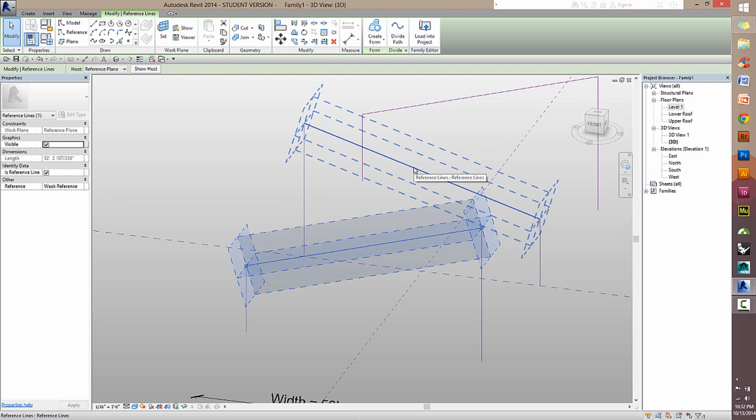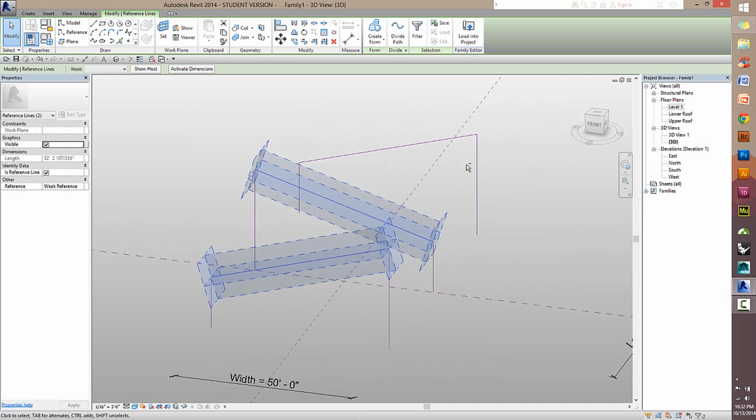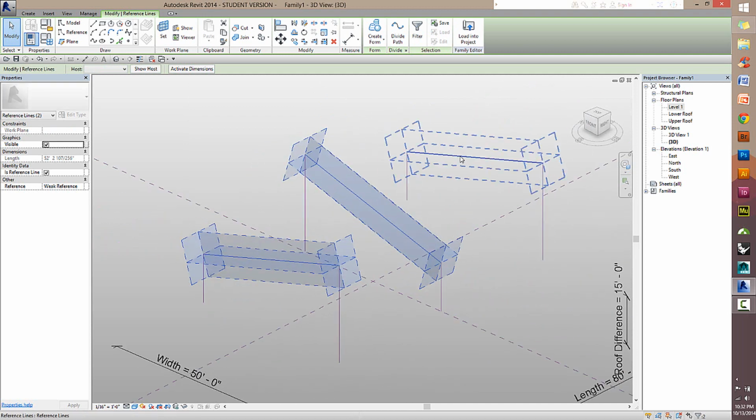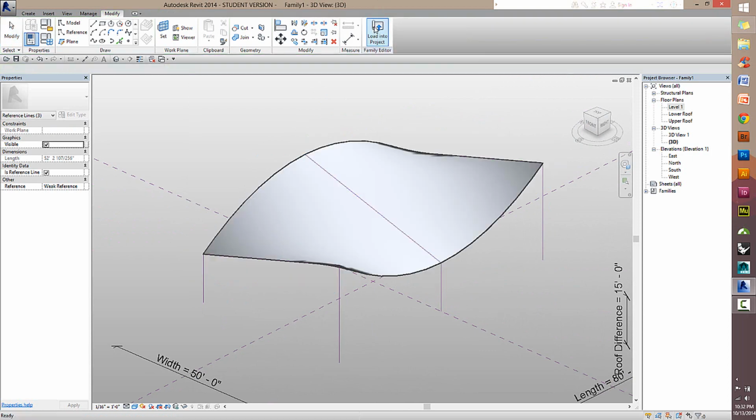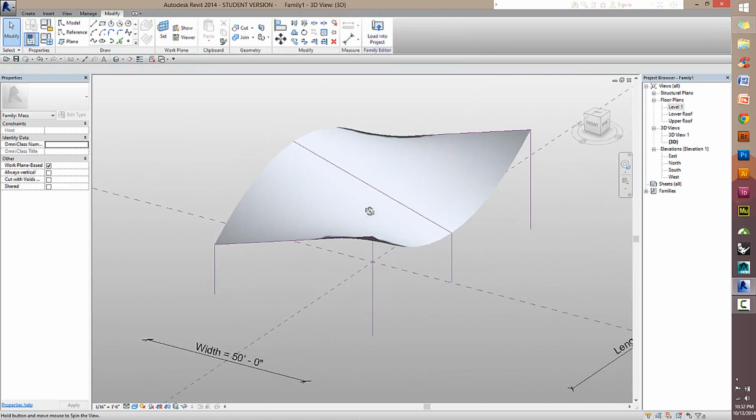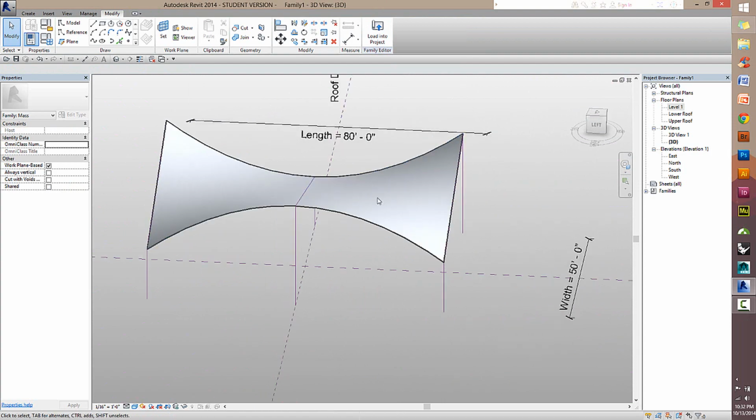I haven't selected it yet, just hit Tab once, and now just that one segment is highlighted, so I know it'll select. And then I'll hold down Control, so I get this little plus key next to the pointer, which lets me know that it'll select multiple objects. Now I have those 2 selected. I'll do the same here. Click this Create Form button,